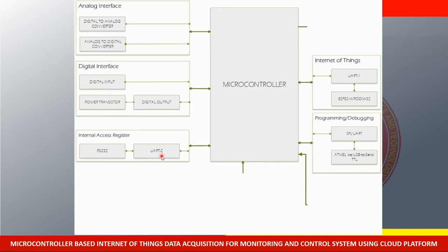So, yung Atmel-ICE, for it to program your microcontroller, ang communication protocol nun is SPI, okay? In any case na hindi tayo gumamit ng Atmel-ICE, we're going to use the UART or the bootloader. So search nyo yun ha, what is communication protocol, what is bootloader. Now UART, if we use UART, we're going to use the USB to serial TTL. In any case na mag-use SPI tayo, Atmel-ICE. So the question remains, what is the best?